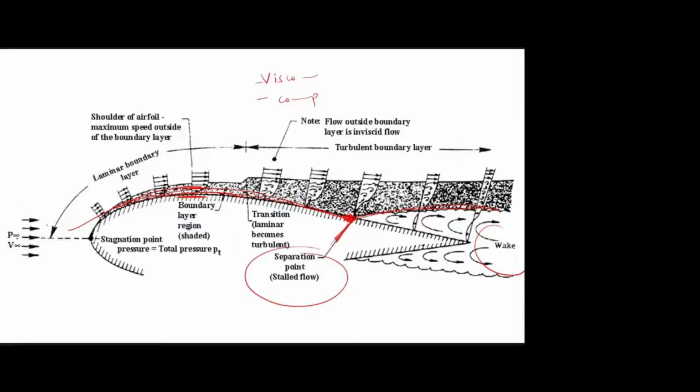Here the flow hits the leading edge, so we have a high pressure region, and behind that there is a wake, there is no flow at all, so we have the low pressure region. Because of this pressure difference, here high pressure, here low pressure, we are getting the force in this direction. Always force will be from high pressure to low pressure. That force is called drag force. Is that clear?